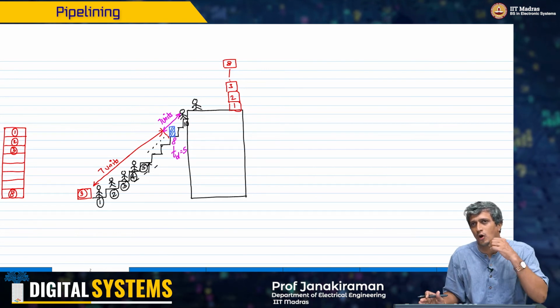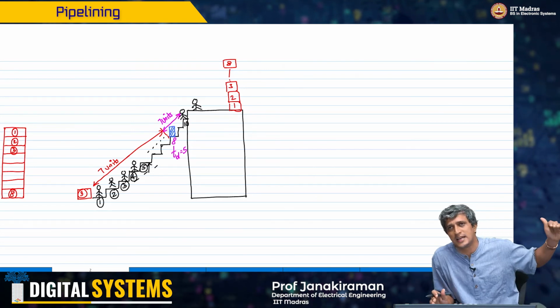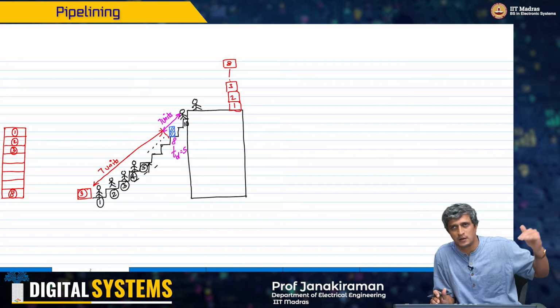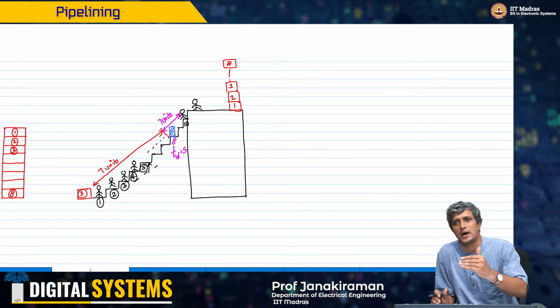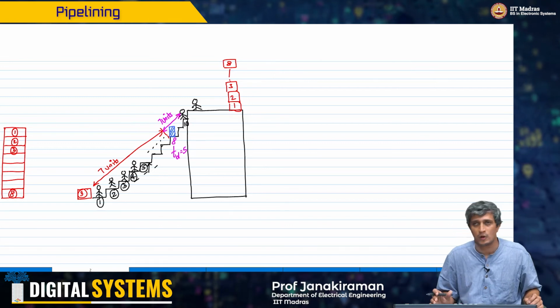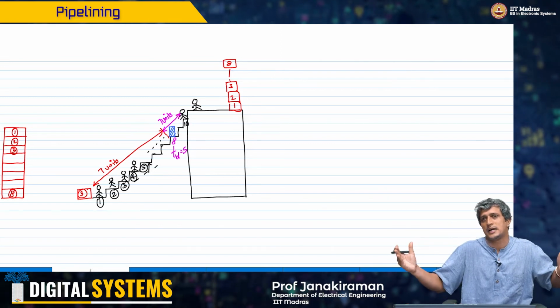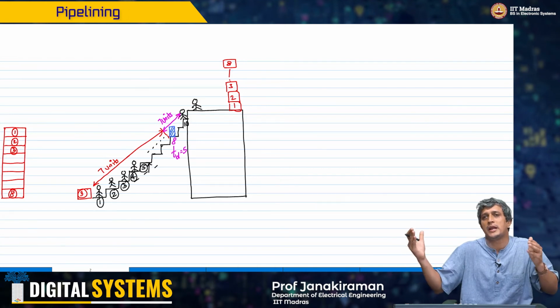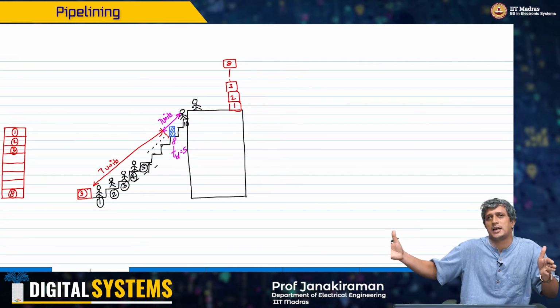So this is what we call static timing analysis. There is a maximum delay, right, through that circuit, or the critical path delay, which will determine how slow that circuit can be, and therefore worst case that the output will be ready only after that delay.